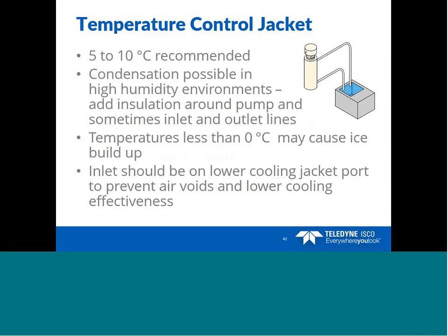The inlet into the cooling jacket should be on the lower side. Having fluid enter at the lower side will push fluid out the top and also push air out the top, and therefore prevent air voids, which could reduce the cooling effectiveness.